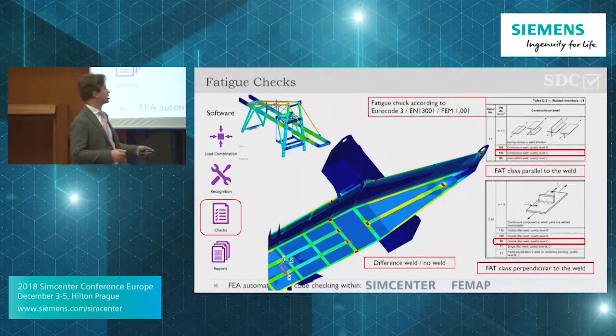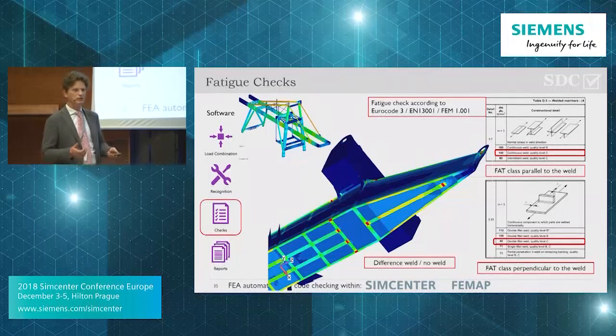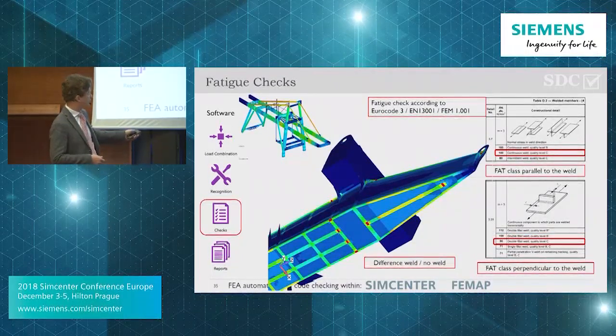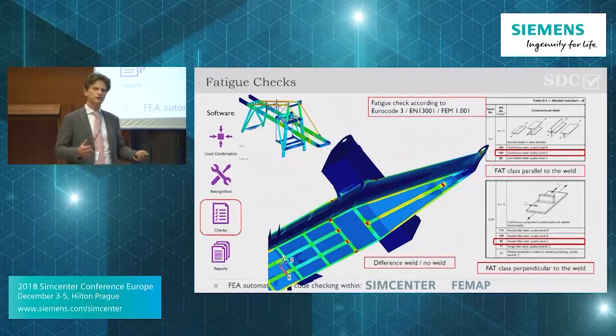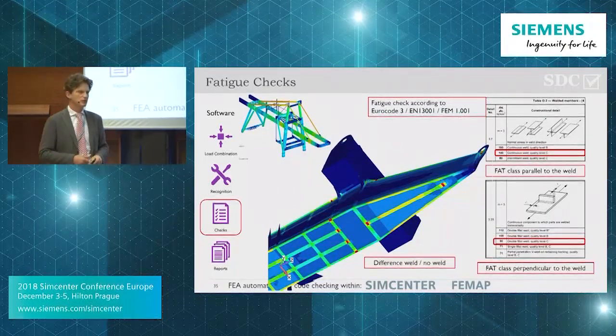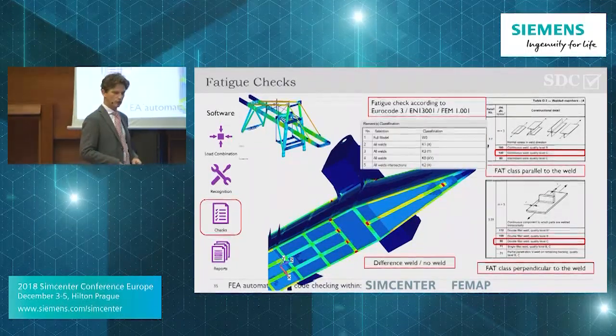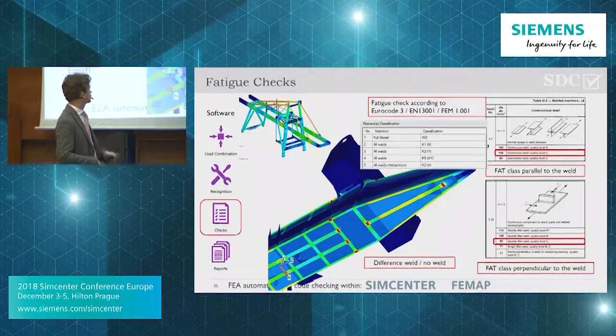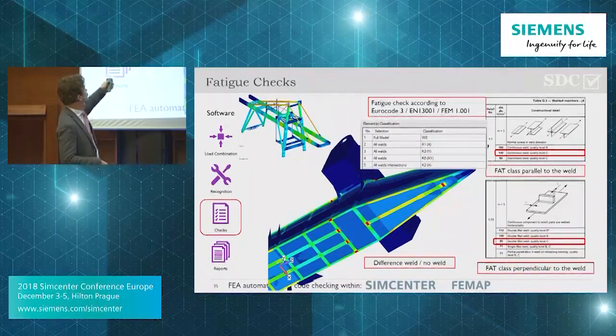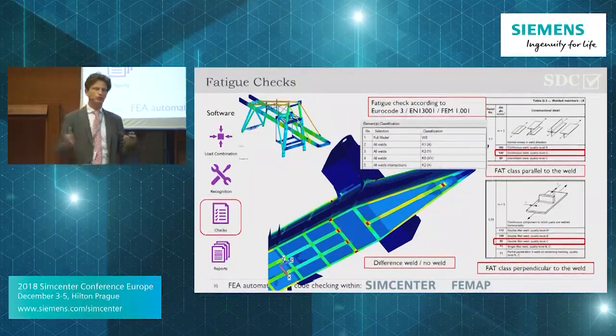So you can take that into account as well, and then you get really realistic pictures like these, where you have at endings of stiffeners, you have overshoot in fatigue resistance, while everything else, so the non-welded, is almost fine. Everything is fine. And this works not only on plates, you can also do this on beams or volumes, whatever you want.